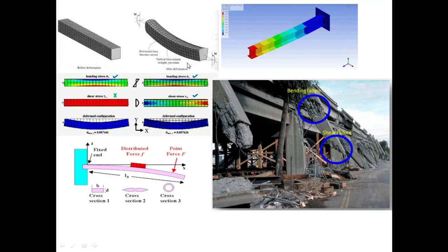If you look at this picture, what I have done is I've taken different pictures and tried to put them in this frame. And here, this is a rectangular beam. So one of the assumptions that we will be considering here is that this beam is basically made up of fibers. We assume that the beam is made up of fibers, and you can see those fibers are running along the length of this beam. So one of the assumptions is this.